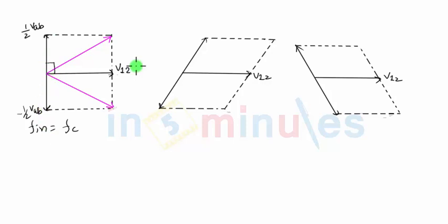And when I draw the resultant phasor, this is where we talk about the next important point. All we have to do is add the voltage on the primary side and the voltage on the secondary side. So when I add the two voltages of the primary and the secondary side, using the rectangular law of addition of two vectors, we get this vector, which is the resultant vector.